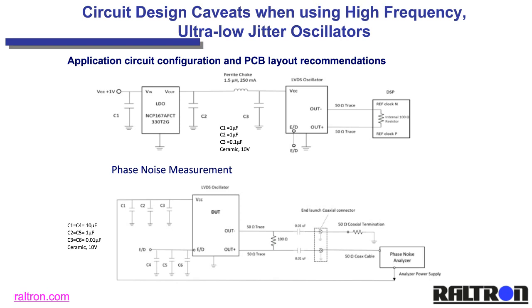Every time we started such a conversation, in general, it turned out to be about what kind of circuit is being used for making the phase noise measurement. Again, this type of LVDS circuitry must be balanced and the impedance must be correctly matched on the output. If not, the results are not correct.